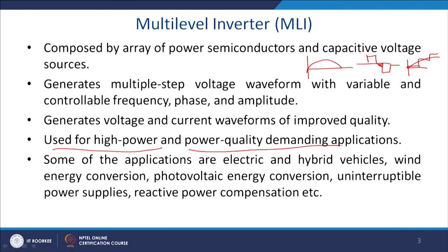Since the cost of power electronic devices goes up with the rating, we need to increase the power handling capability by connecting devices in series. For this reason it is used for high power and high quality power management applications, and it is one of the basic needs for our FACTS devices.